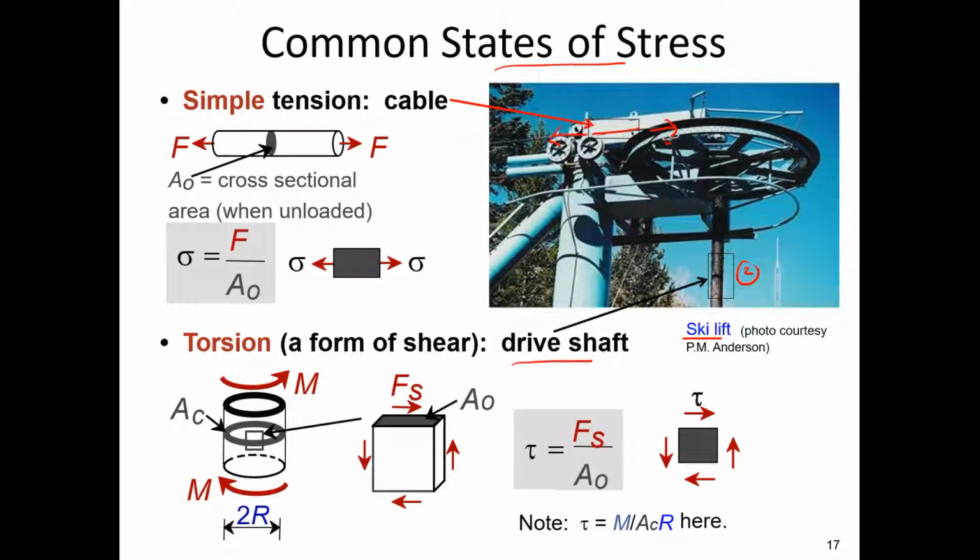Number two, which is here, the drive shaft. This drive shaft is continuously twisted in order for this wheel to move. So this drive shaft experiences torsional stresses.